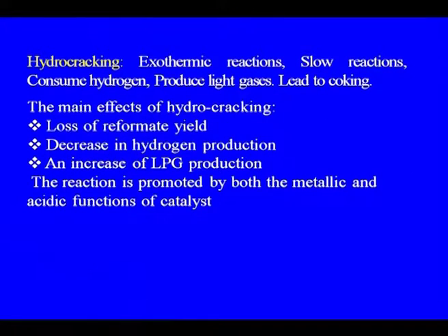Hydrocracking, as I told you, is an exothermic reaction. The main effects of hydrocracking are loss of reformate yield, decrease in hydrogen production and increase of LPG production. The reaction is promoted by both the metallic and acid function of the catalyst.